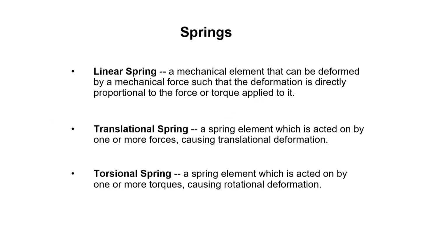Now, springs also can be of different types. Let us say linear springs, which are predominantly for axial movement, and where the force versus displacement linearity is maintained. But there can be other springs which are non-linear, like you can have a spring like this, or a spring like this. This type of non-linear spring is called a softening spring. This is of course linear, and if suddenly the stiffness increases, then this becomes a hardening spring.